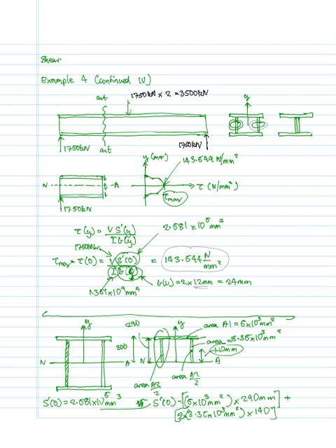So that shear stress would be acting downwards at both of the webs, and then to convert that into a traction per web, you would do 143.64 multiplied by the thickness of each web, which would be 12 millimeters. And that would work out, if you wanted to, the traction or the force per millimeter flowing down the web at the point of the cut.